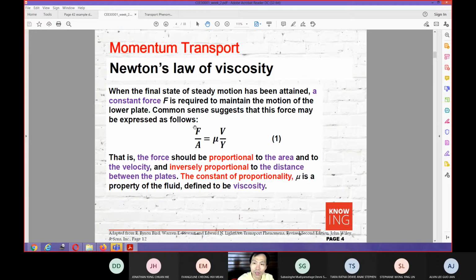It is very important that you go into your notes as I go into the units, and see the consistency of the units. Dimensional analysis is important here to find out the unit for the viscosity. You need to make sure that the units on the left hand side are the same as the units on the right hand side. Based on that calculation, the unit for the viscosity will be Pascal multiplied by second, or in SI, kilogram per meter second.